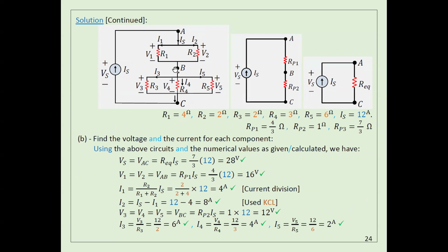Same thing here, you have the total current, so you have a formula, so you can get the current here, the current here, the current here. Here we don't have a formula for 3, but it's very simple. Here I have I total. So this total current I is going to be divided between 3. It's going to be a little bit complicated for 3, but what you can do is calculate the equivalent for these two resistances. Now you have two resistors, this one and these two together.